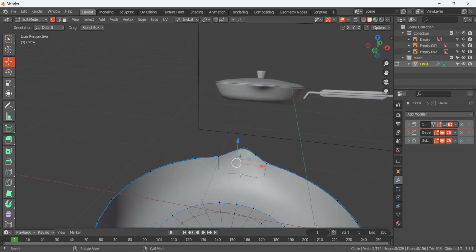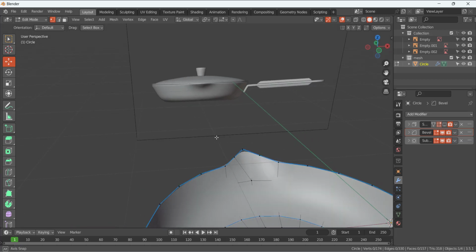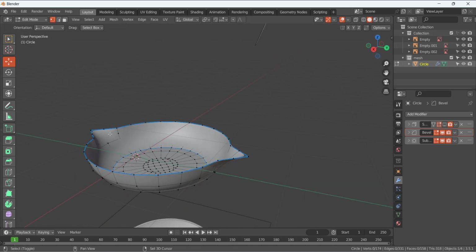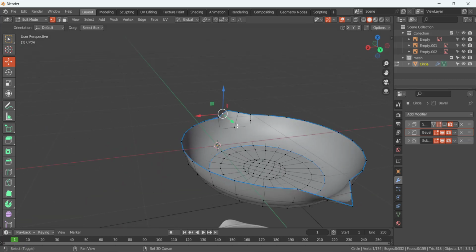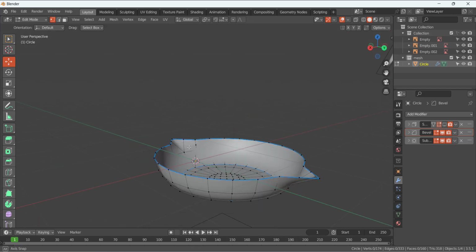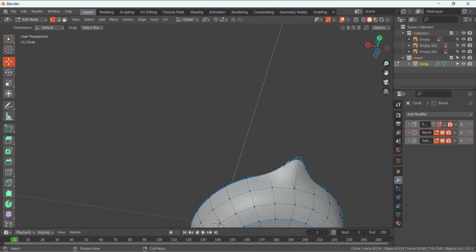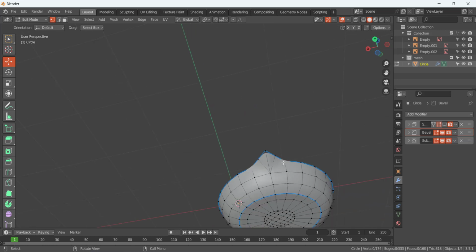and now we can connect this vertex and this with this vertex. We can use the K to add a vertex here, and also K and add a vertex here like that. We can also select this one, and also press the J to join them. We can also use that, and J to join them. Okay, it will edit these loops here. So now it will make it a more circular shape at this point.